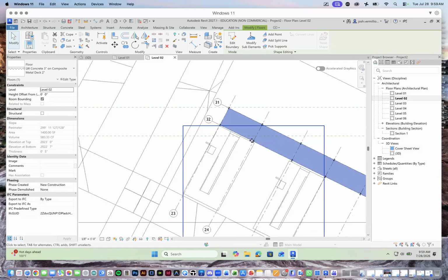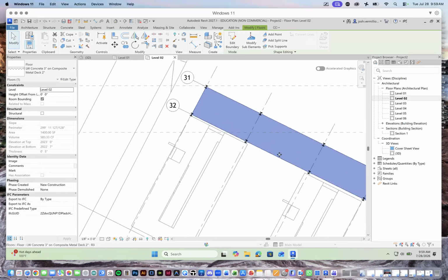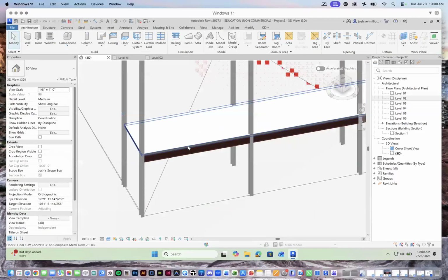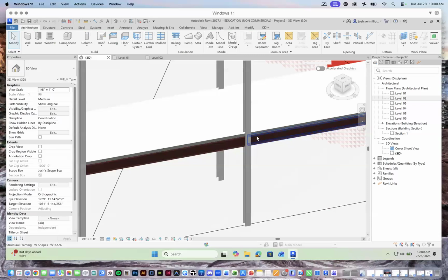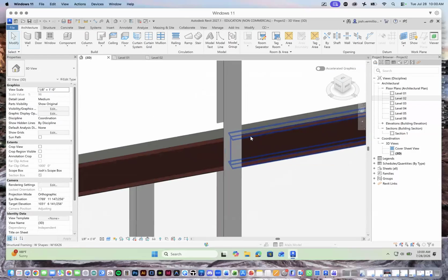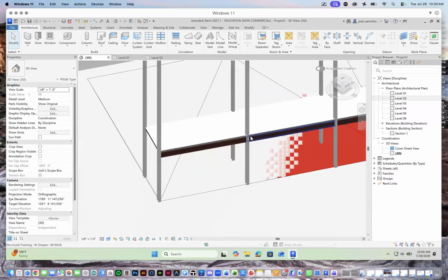You can see here that I can quite clearly see the floor slab, and in the 3D view, I can see it as well, right? Okay, and it's sitting right there on that beam. Remember, we moved the beam down 5 inches, taking into consideration 3 inches of poured concrete on a 2-inch metal deck. So that worked out really well. Thinking a couple steps ahead.